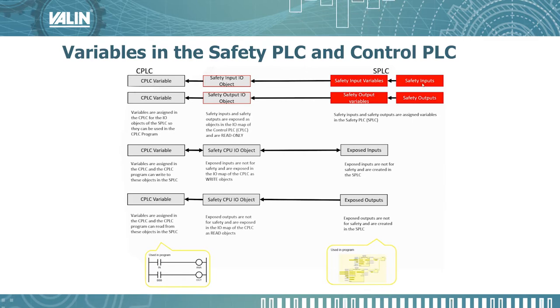Note that all of these safety inputs and safety outputs, even when you create variables for them in the control PLC, are not available for writing to the safety PLC. So you can monitor them, but you can't write them. They're read-only.